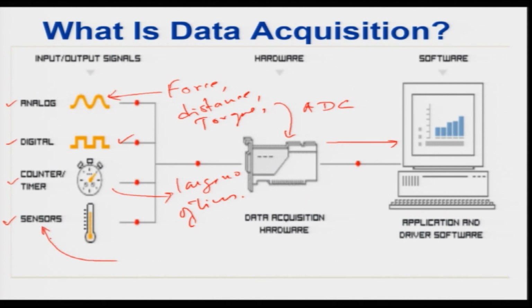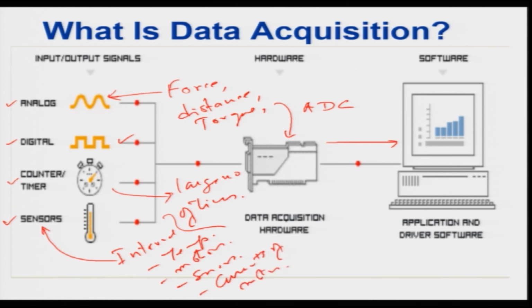Now, internal sensors are there in the robot itself, for example, measuring temperature. When the robot is operating, it is measuring the temperature of the controller and the motors. So, temperature of motors, okay, because if the motors become too hot, then there is chance they can burn. They are measuring the currents of motors. So, internal sensors are there in the robot itself, which are internally monitoring the performance of the robot in terms of temperature, then in terms of the currents that the motor is taking.